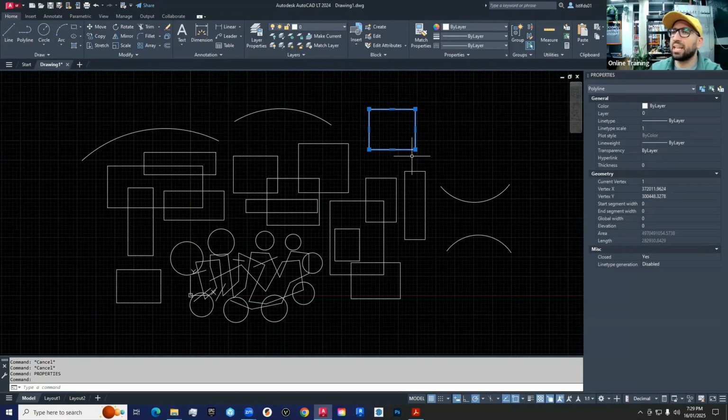So if you select a rectangle in AutoCAD once created, it's called a polyline. It's a bunch of connected lines. Poly means more than one. So there are more than one line connected together. And right there, you can check the area and check the length of this one. So if you want to know the area and the length of your objects, you're going to find them right there in millimeters. That's why we have a lot of digits right there, depending on the scale you're currently using.